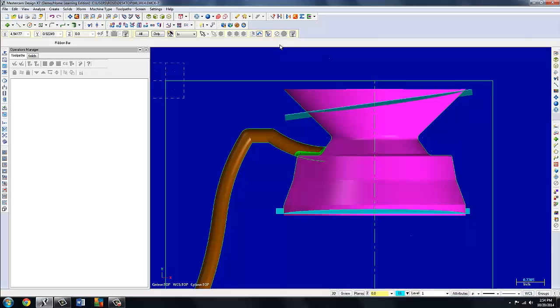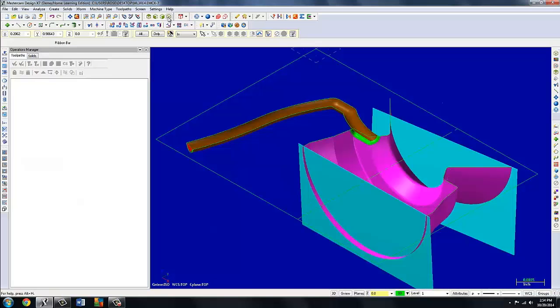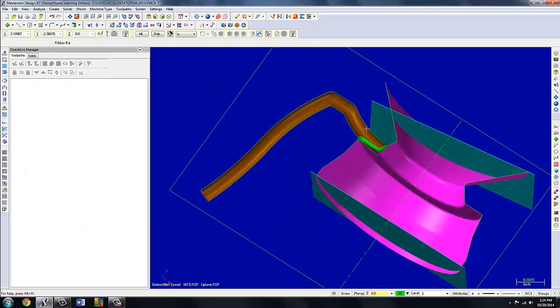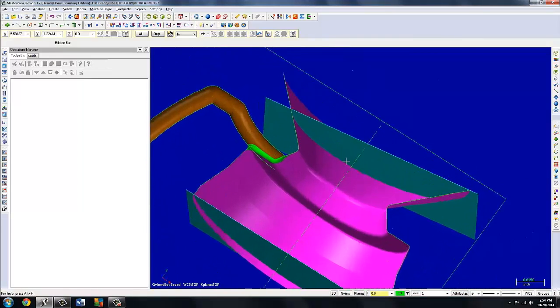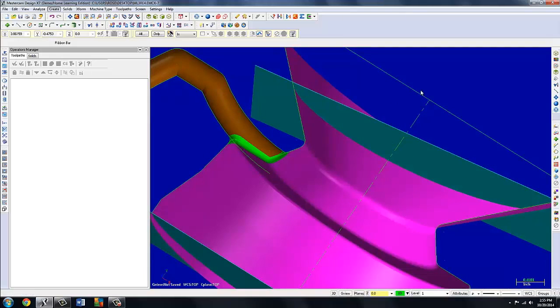Go to my fillet green color. I'm going to go back to isometric, and I'm going to work the top first. Again, I'm working from the inside. I tried working from the outside and was very unsuccessful. I've been testing various logic in terms of selection process and order, and I'm still not getting much consistency. So again, this fillet command is very temperamental and very automatic, and you have to try to get into the mind of the software. But some of the things I have figured out is that you do it from the inside, if that's where your fillet's going to be.